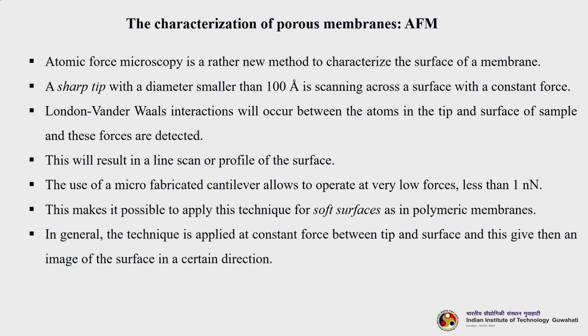AFM is a rather new method to characterize the surface of a membrane. There is a sharp tip with a diameter of almost 100 angstrom, very small, very thin, which is scanning across the surface. Okay. In SEM, the electrons scan the surface of the sample, but in AFM there is a tip. The cantilever is holding a tip, and that tip is scanning like this, with a constant force.